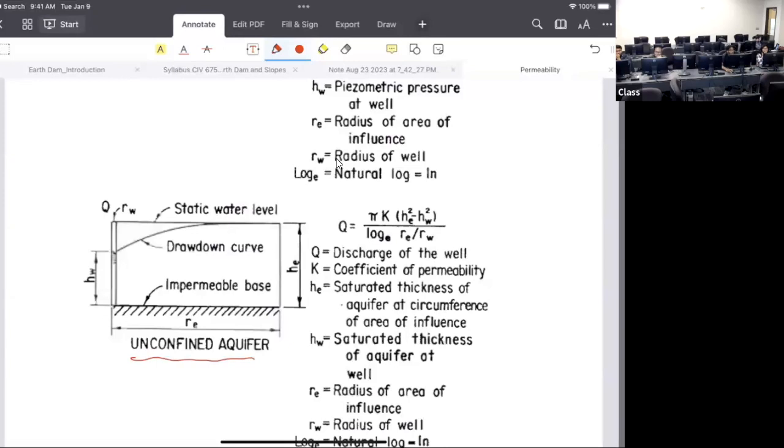Artesian aquifer: the water layer is bounded by two impermeable layers, up and down. So it's under pressure, right? It's pressured water. So if you have a borehole or something, water should flush out, right? Any idea of the artesian aquifer? Anyone been to Little Rock? There are some aquifers where you can see water always comes out from the ground. I think Little Rock has it in Arkansas.